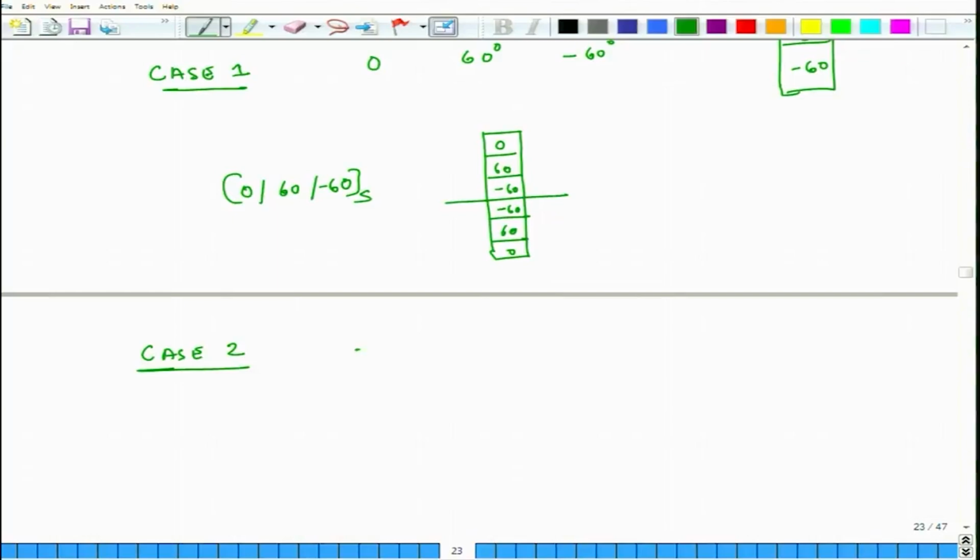Case is plus minus 45, 0, 90. Okay. So, you have 4 layers, 0 degree layer, 90 degree layer, plus 45 degrees layer and minus 45 degree layer. So, here also we will get quasi-isotropy, but B will not be 0.